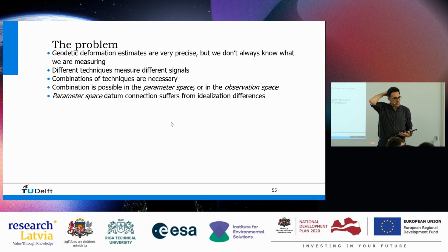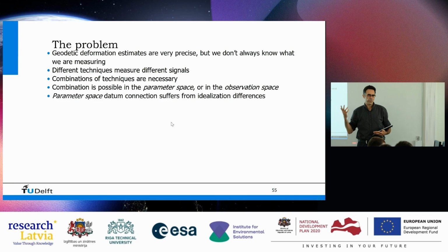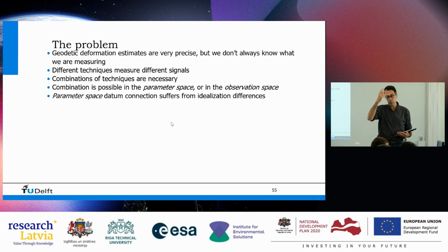Also, in the past, when InSAR started, there were many studies where the InSAR results had to be validated. People didn't really trust it. It was new. So they said, let's compare it with leveling. There are hundreds of comparisons with leveling, with GPS, any other techniques. The problem is that it was never a perfect match. There was always a difference. That is partly because these different techniques measure really different things. Measurement bolts in a wall are something else than a reflection from a roof.